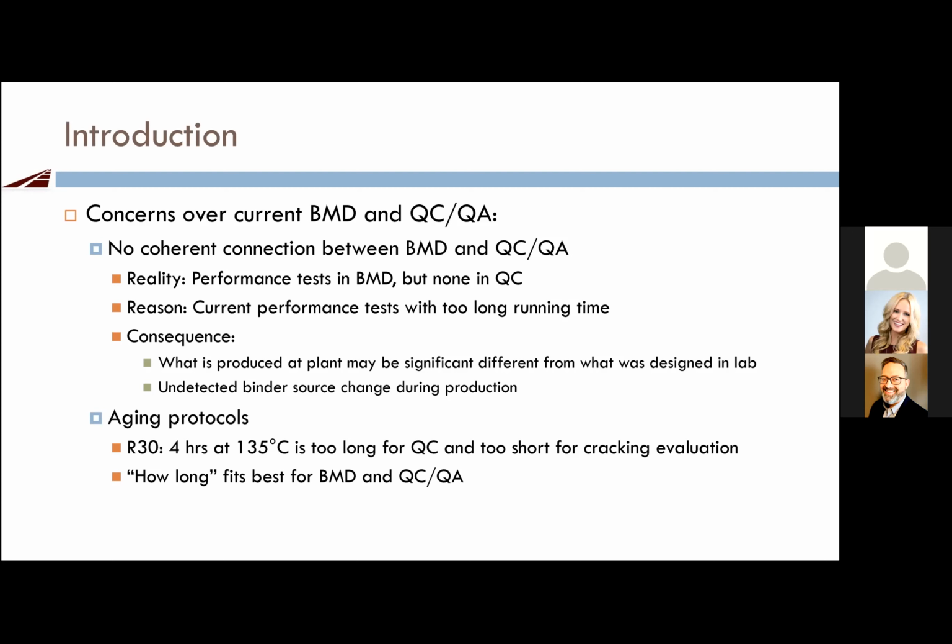The second topic is about the aging protocol. I think most DOTs are following the AASHTO R30 aging protocol. Basically, that is 4 hours at 135°C for performance tests, for rutting tests, and that's what most people use.